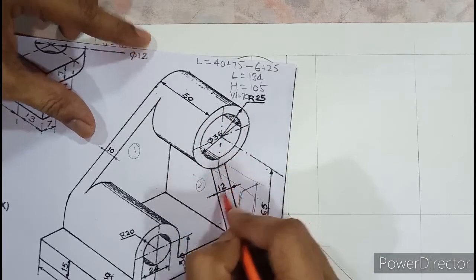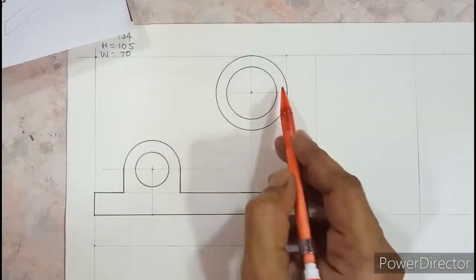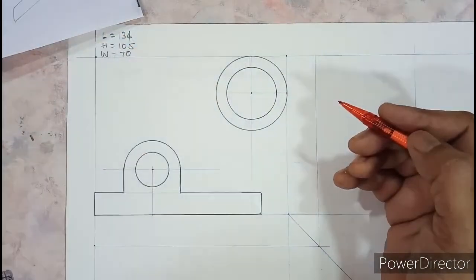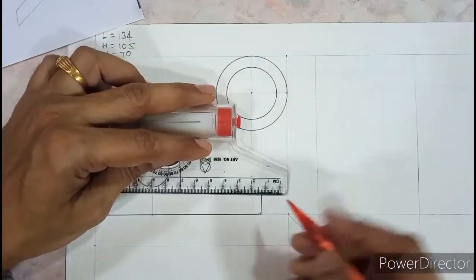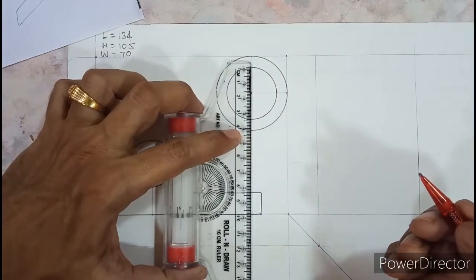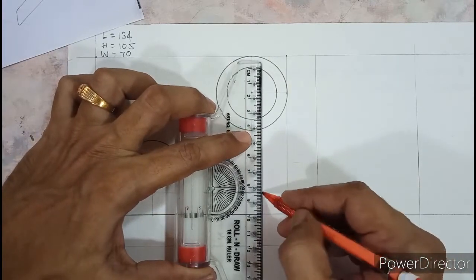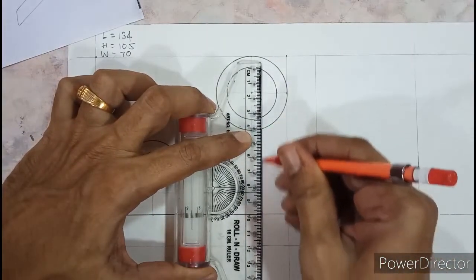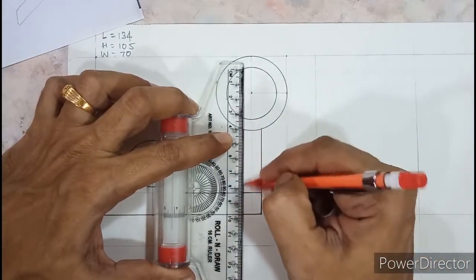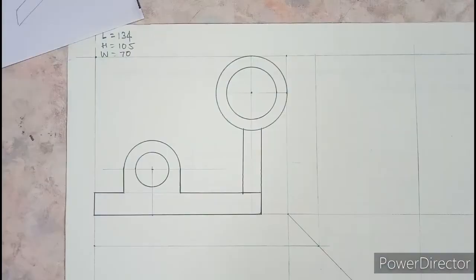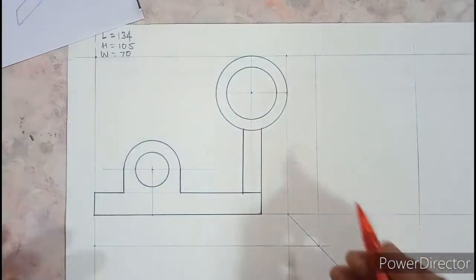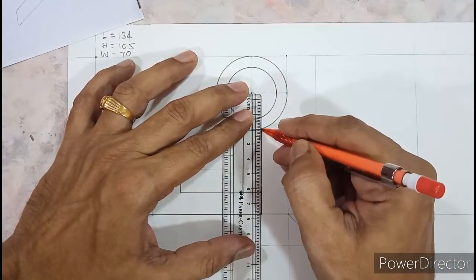So there is a plate of thickness 12 mm connecting the cylinder and the base plate. We have the cylinder here and the base plate is here. We need to connect them by a rib. So 6 millimeter on either side. One side 6 is already marked. We need to mark 6 on one more side. And from here we will extend this beyond further, and even from this side. So you can see that I have marked 6 millimeter on either side.